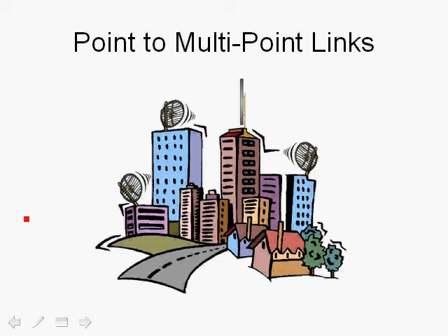Another example of a harsh environment is digital communications over long distance using HF communication, where the ionosphere is used to bounce off the signal to achieve long distance. Certain carrier frequencies are available over a specific period of time, and we have limited bandwidth and signal-to-noise ratio and have to deal with lots of interference.